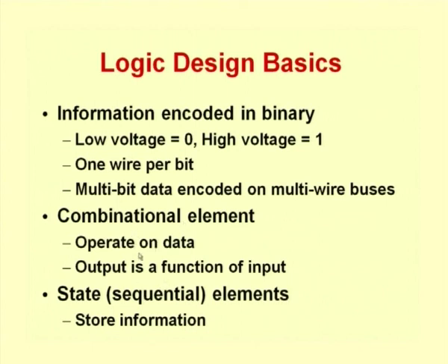And then of course, we will use combinational elements and sequential elements. Combinational elements operate on data and the output is a function of the input. So, using the basic gates, you will be able to generate this kind of circuitry, and then we will use state elements or sequential elements for storing information. So, your design will be a combination of these factors.